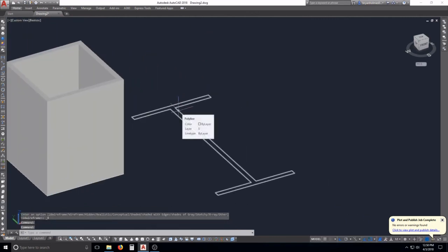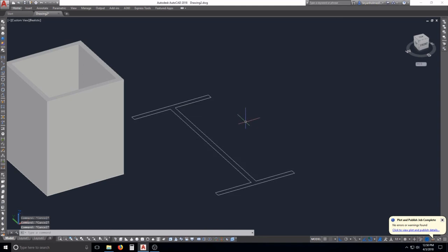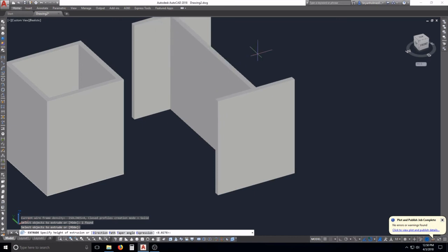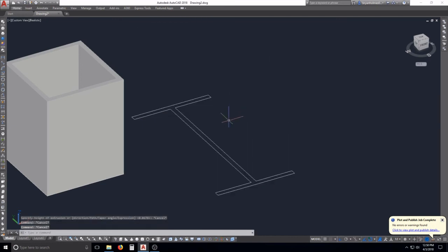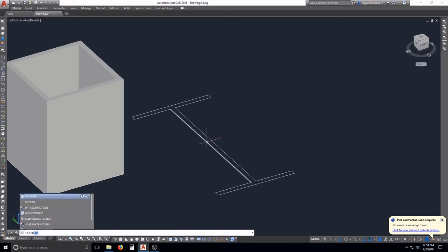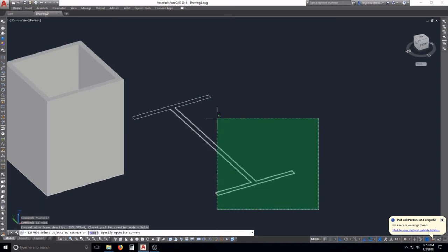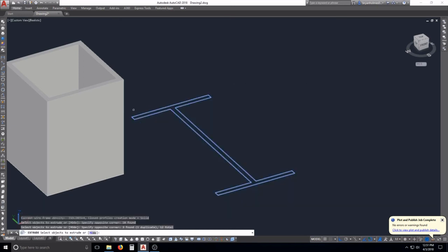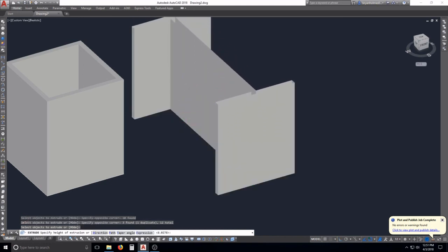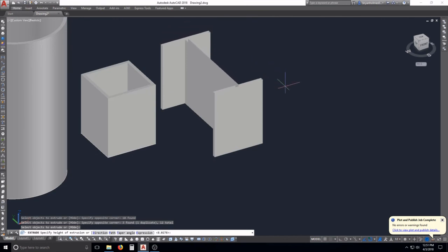Again, you can extrude that face up farther. There's also an extrude command. I'm not as familiar with that one, but we can try it real quick. Let's see, EXTR. And pretty much the same thing, but I think the extrude command is different, in the sense that you don't have to join everything. I could be wrong. I don't know. I don't really use this command. Ah, look at that. Oh, yeah, I see the difference.